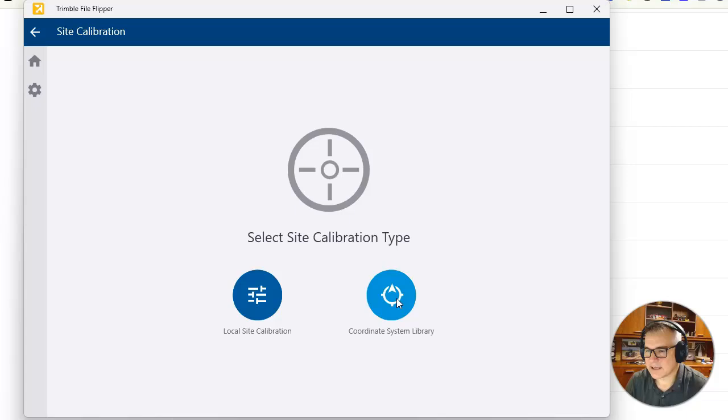If the data's collected in a large coordinate system, like a global coordinate system type thing, you'll have large numbers. The eastings and northings will generally be in the hundreds of thousands to millions. You can easily check that in your file, just have a look. But you should know what coordinate system you're using.